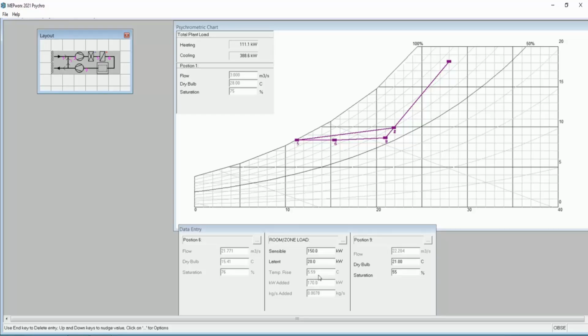A trap a lot of people fall into is trying to overspecify. Trying to specify a temperature rise and a supply condition and a room condition is based on an iterative cycle. It's trying to make 2 and 2 equal 5. You can't do it, so you have to relax some of the data entries, as I did earlier, by entering the 6 asterisks.